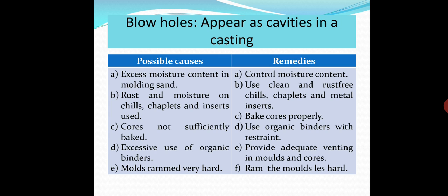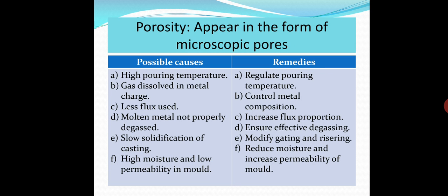Organic binders must be used in proper proportion. Make the ramming proper: ram to a certain extent, not very hard, and provide adequate venting in molds and cores.